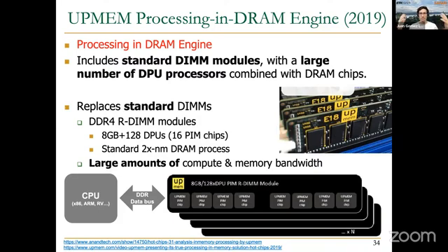One problem with that, and probably all of you are familiar with the von Neumann model, where we have the processor on one side, the memory on another side, and in the middle we have a communication unit. The problem that we have in most current systems these days is that this communication unit is very narrow. Because it's very narrow, it basically behaves like a funnel. And that creates a lot of contention when moving data from one side to the other. One way to alleviate this data movement bottleneck is called processing in memory.